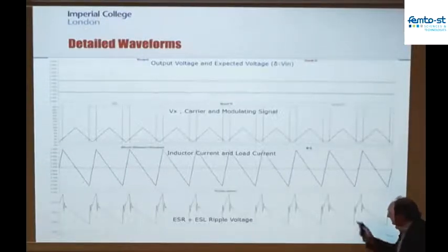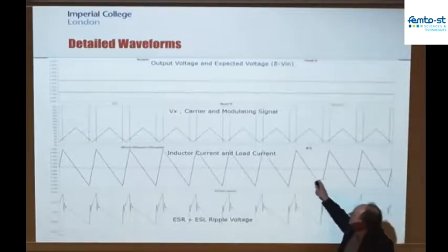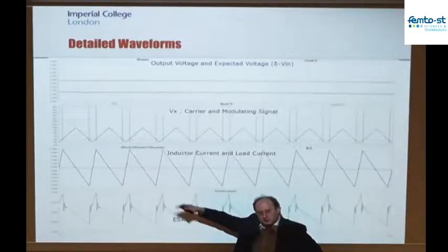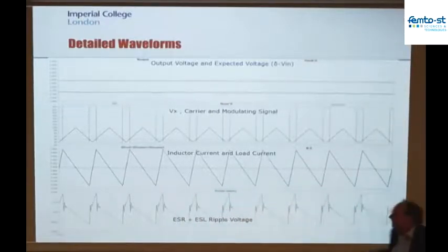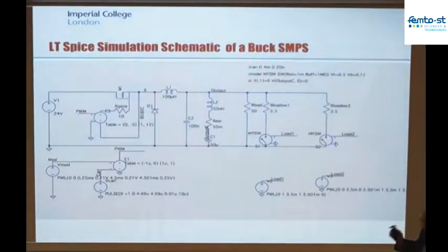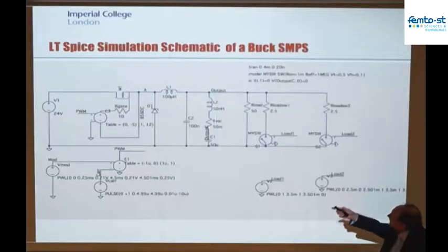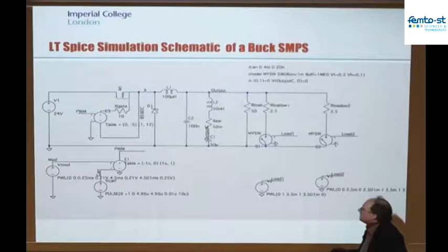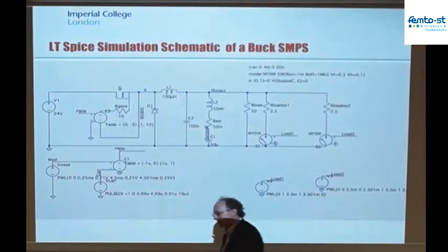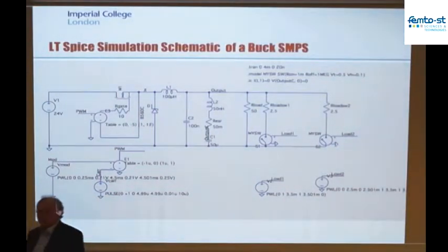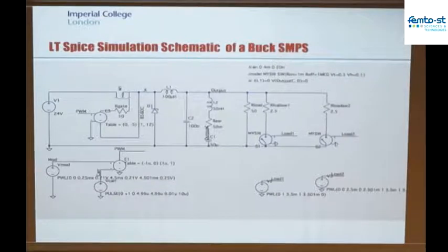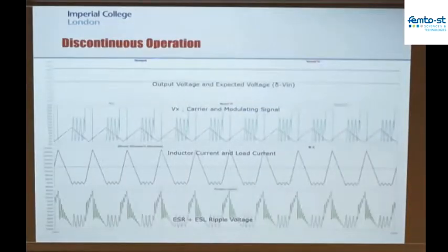And the interesting thing is the shape of that voltage ripple, because it is not purely integrating, as you would expect, the AC component of the current, because that's what a capacitor should be doing, integrating the current to give you voltage. In actual fact, I'm putting a triangular shaped current into a branch here, which is not just a pure capacitor, it has a resistor and an inductor, purely because I can't build an electrolytic capacitor that is a perfect capacitor. It has those parasitic components, and if I put high frequency currents into it, then I will have to see those high frequency components coming out into the output stage.